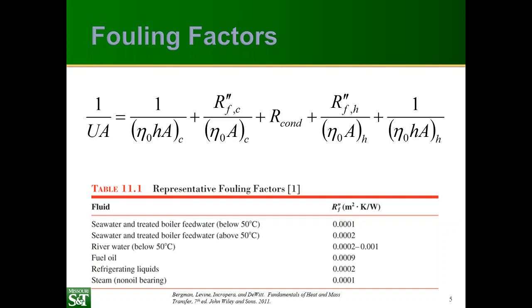But if you only know the inlet conditions and not the exit conditions, then you have to guess delta T2, and so it becomes a long iterative process. So it's not always that good of a design tool for that kind of behavior. However, we're going to talk about effectiveness NTU, which is a little bit more effective for that type of analysis in another presentation.